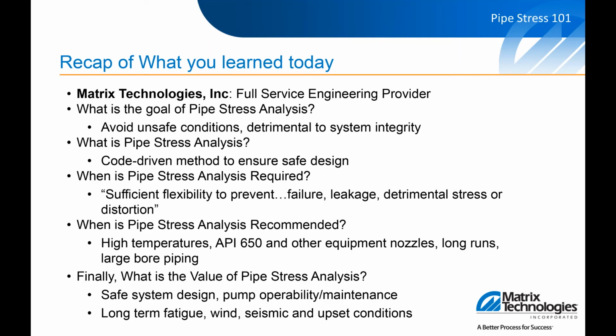Knowing when to apply pipe stress is a little bit of an art form, but hopefully we've shown you some areas of sensitivity today. So when is pipe stress analysis recommended? High temperatures, API 650 tanks, equipment nozzles, especially rotating equipment, long runs, large bore piping.